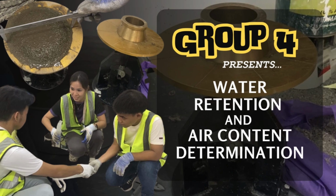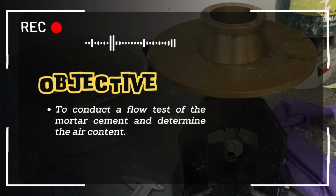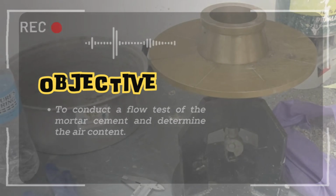Group 4 presents water retention and air content determination. This test method covers the determination of the air content of hydraulic cement mortar. Our objective is to conduct a flow test of the mortar cement and determine the air content.